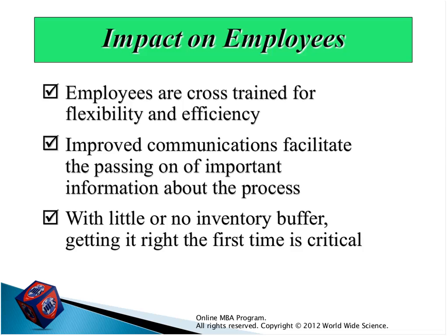As I told you, defective products are waste. When workers produce units one at a time, they test each product or component at each subsequent production stage. Machines in work cells with self-testing Poka-Yoke functions detect defects and stop automatically when they occur.